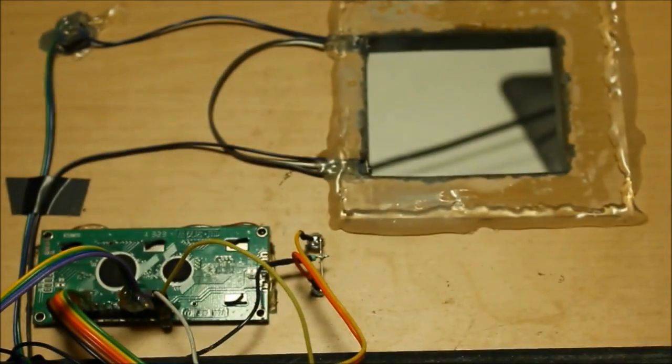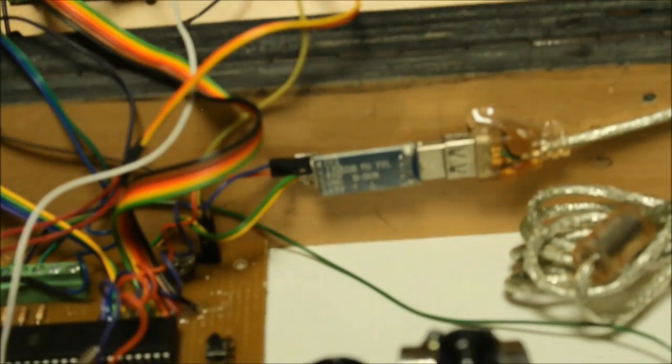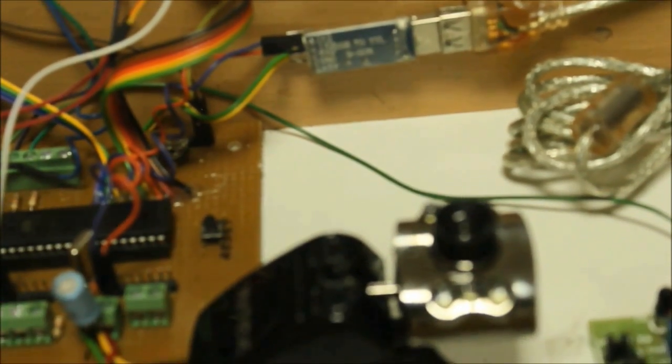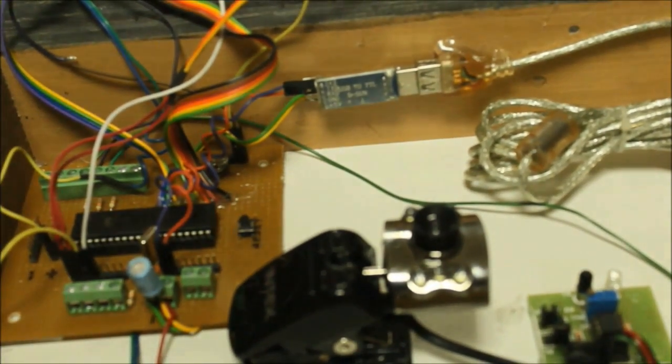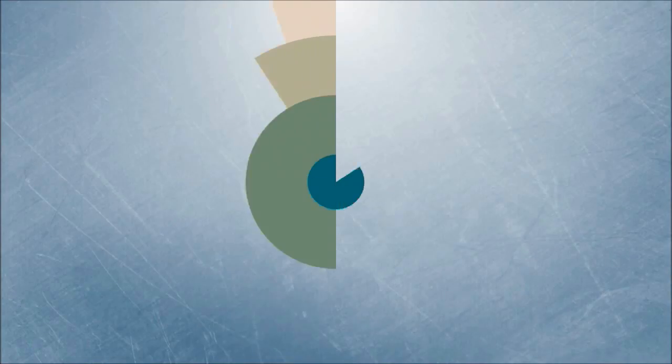The setup consists of a 16x2 LCD screen, a slot for placing the ID card, and sensors to detect if the ID card is placed properly or not. It also has a microcontroller and a web camera. The microcontroller is used for monitoring the sensors, interfacing the LCD, and serial communication between the setup and the computer.